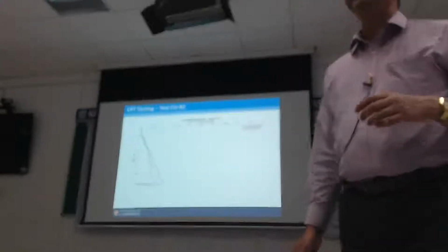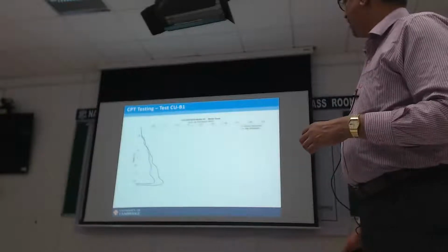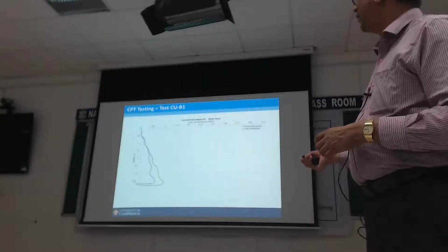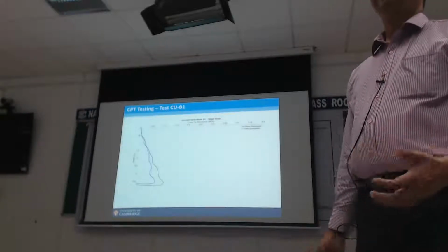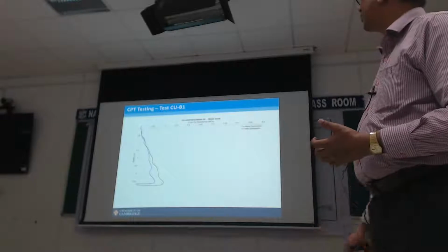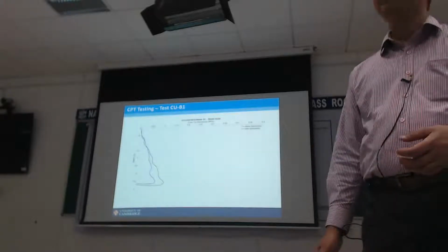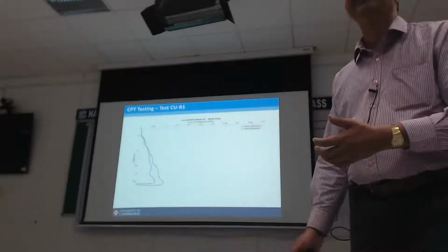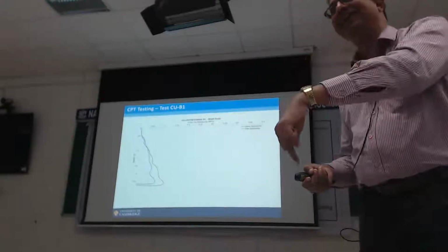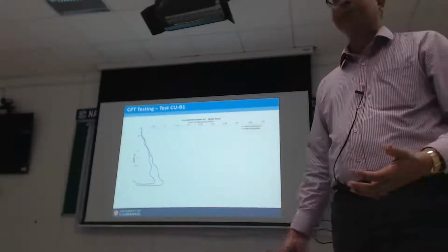Now let's look at the 1G test, where we push the CPT, the raw readings say that we got hardly any cone tip resistance. It's about at 2 meters, about 0.05 megapascals. In other words, I got about 50 kilopascals. What do you expect? I got soil this deep and I'm pushing CPT. Of course, it's not going to give me much resistance.